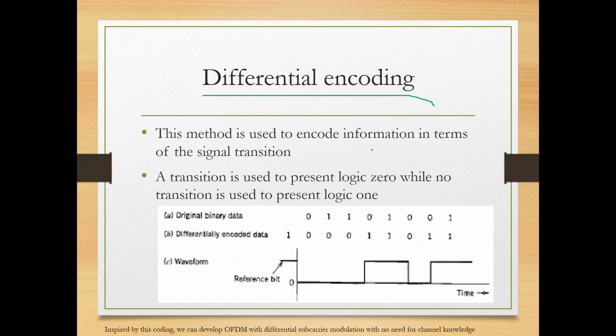The phase of the carrier at the demodulator might differ from the phase of the carrier at the modulator. So in such cases where you have a difference between the phases of the carrier at the receiver and the carrier at the transmitter, you cannot use normal modulation schemes. You need to use something differential, because this produces non-coherency, and non-coherency kills your communication if you don't handle it.